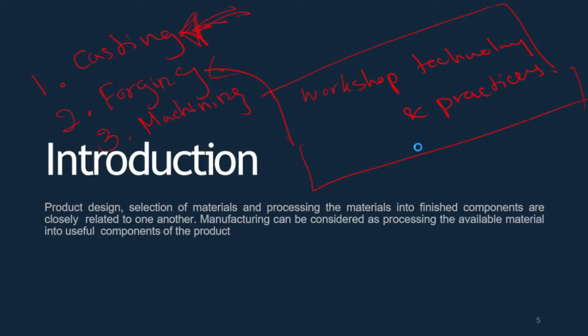These are the advantages. Then as a disadvantage, we have high energy requirement for this process, because we need to heat this raw material. Then after that we can do our hammering process and create a final shape.